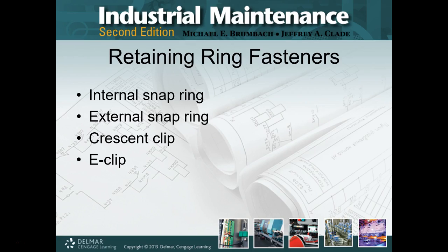The external ring is perfectly round on the inside, so it can slip over the shaft. Internal snap rings go inside, so that's why you want the perfectly round. If it's perfectly round on the outside, it's an internal. If it's perfectly round on the inside, it's external. Makes perfect sense, right? Not. Use them a few times, you'll know it. Okay, just please believe me on that.